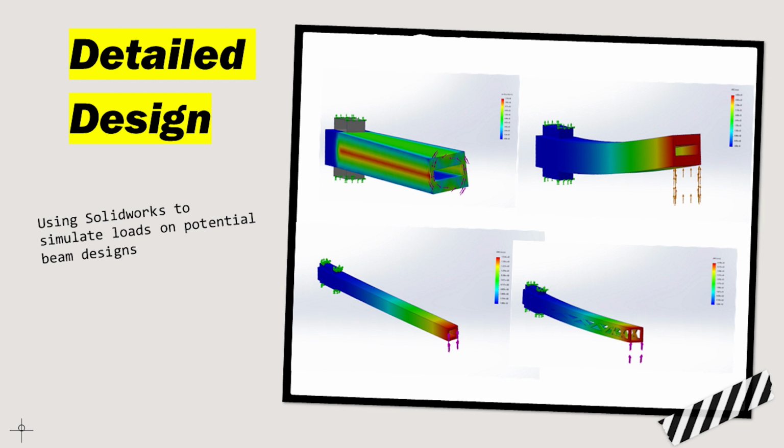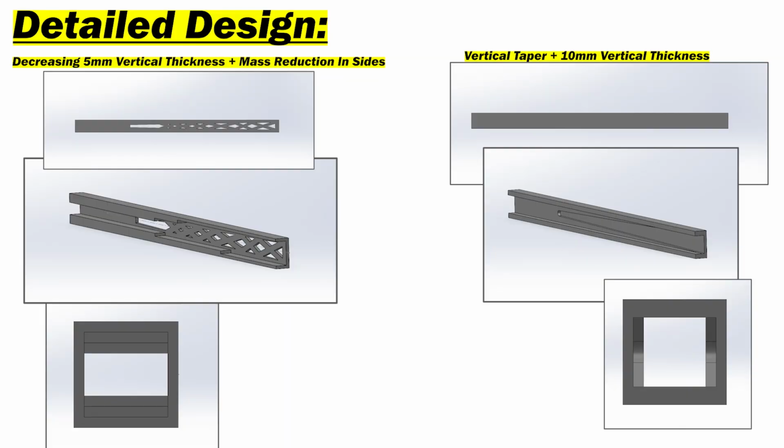After a torsional test was conducted, we also found that the parts closest to the neutral axis experienced the most stress in torsion. This meant that we couldn't remove too much mass from the sides as torsional strength would drop dramatically. We tested a few different methods of decreasing thickness along the beam, and found that the best solution was using 2 extra slices of foam rod on the top and bottom of the spar that got thinner along the spar, which saved a significant amount of mass.